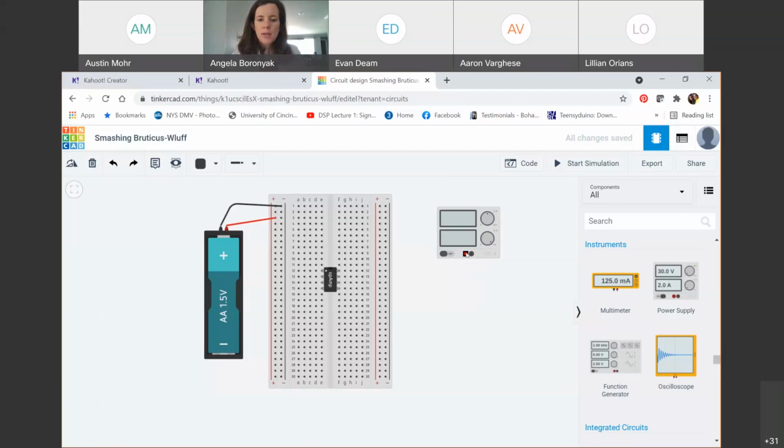So I want my positive here to go in the row that's my positive power. And I'm going to click places here so that it's a little more user friendly. And I'm going to give it a red wire because that is the positive from here. It's different than the 1.5 volts here. So don't connect your positive 15 where you want positive 1.5 volts for the end. That's a very different power, right?